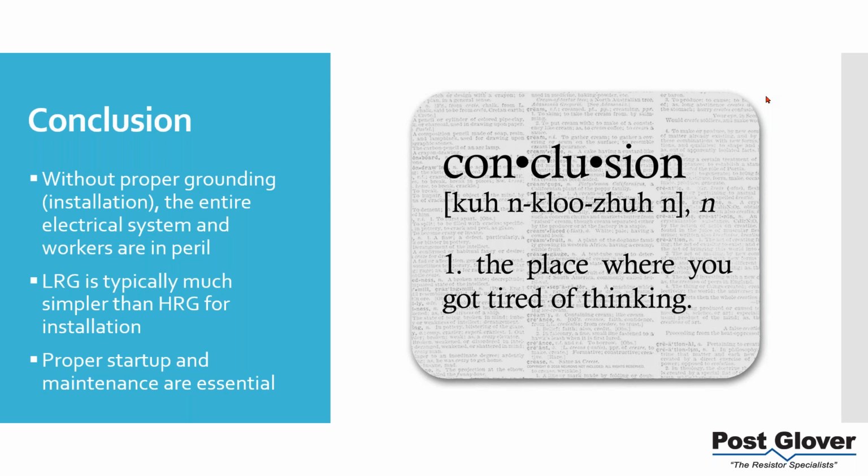I'll give you a short answer. Actually, to be honest with you, we're going to be going over this in a couple months and get into detail about this question. But essentially, you need a much higher ground fault current in a reactor. Typically it's 20 to 65% of your three-phase fault current that needs to be the ground fault current of your reactor. So there are potential issues with that. It's much more common at higher voltages, like 35 kV and above. But for industrial applications, it's much more likely to use a resistor.